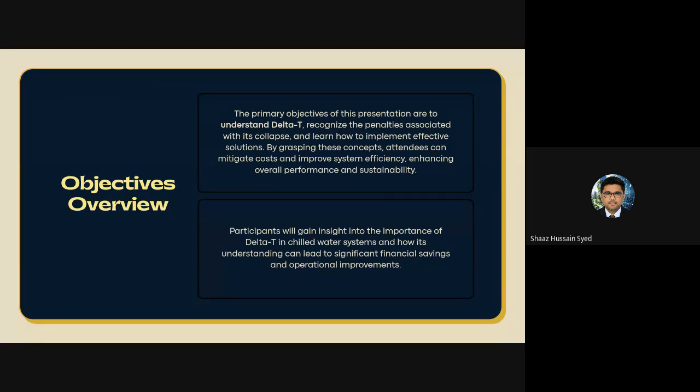The major issue is low delta T, in which your return temperature is lower than what is expected. So why does this phenomenon occur? And why do these district cooling companies charge penalties when this low delta T syndrome occurs in your system or in your facility? And the reasons behind this.